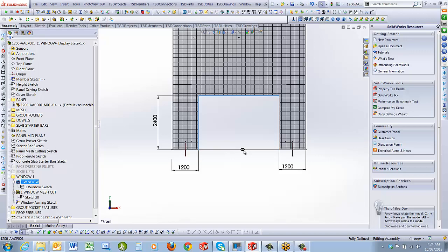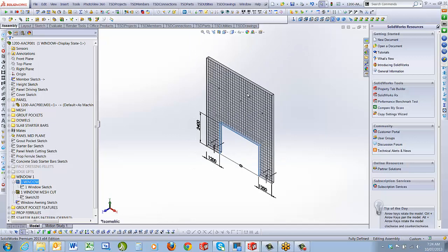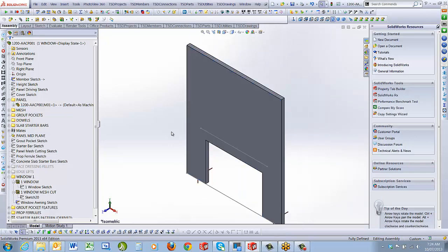It's up to you on how you do your concrete panel design, but remember that if your concrete panel isn't thick enough, you start inducing cracks and things like that. So it can be a bit messy. I've seen different situations where customers have cast in SHS either end to stiffen the whole thing, and then when they put the panel in, they cut the SHS off and then put the concrete in. It's just one of those things. Different design for different companies and different engineers. All right, so that's that as far as windows go.